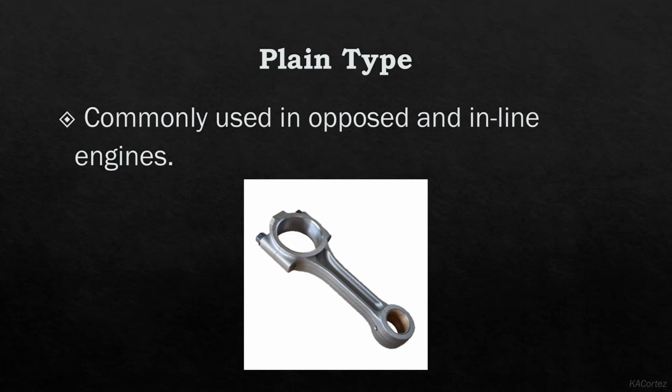The end of a rod attached to the crankpin is fitted with a cap and a two-piece bearing. The bearing cap is held on the end of a rod by bolts and studs. To maintain proper fit and balance, connecting rods should always be replaced in the same cylinder and in the same relative position.